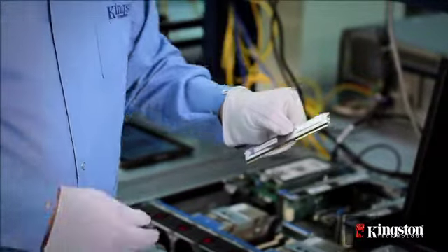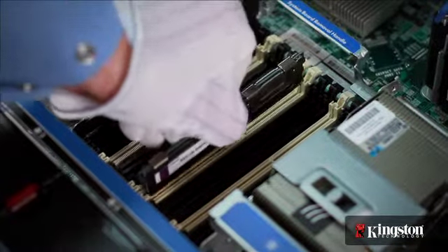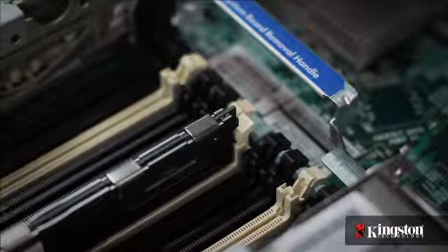When you install the memory, be sure the module key is correctly aligned with the socket. This will indicate whether you've correctly oriented the module in the socket. When it's correctly lined up, it's then safe to press down into the socket. The clamps on either side of the module will automatically fasten when it's correctly placed. Be sure to press firmly on both sides to get a good, even seating.